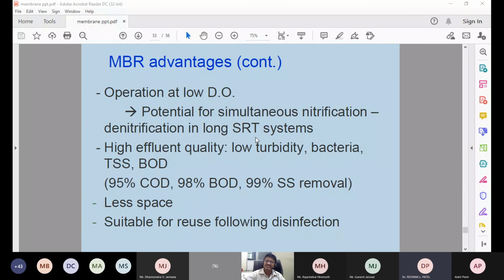Sir, last week I tested one commercial sample from a local RO water manufacturing industry. My observation was that hardness was very low, and surprisingly the chloride concentration was very high, which is not what we expect in an RO system.